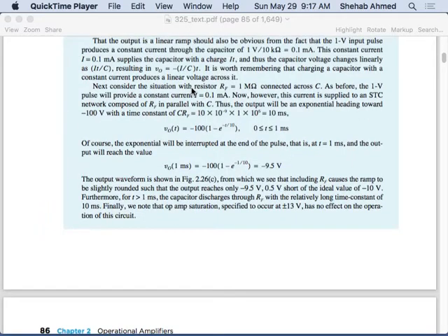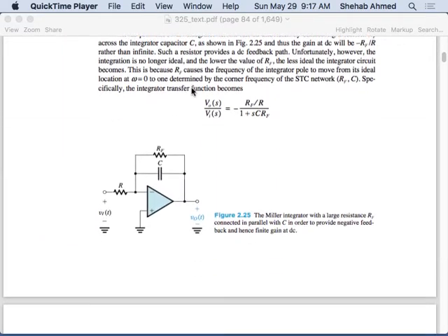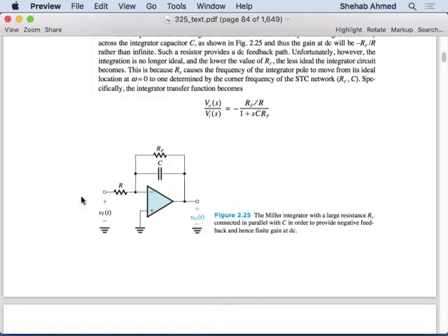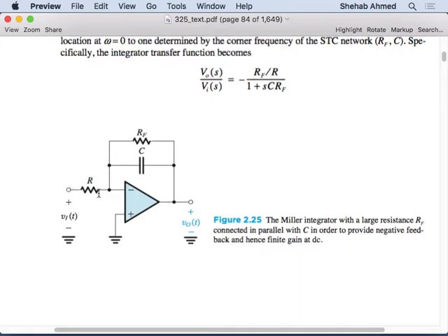We left off last time. I think we were talking about the integrator, and we said that this integrator circuit ideally does not have this resistor in the feedback, right? Ideally, what is the current flowing through here equal to? The current flowing through the resistor. Forget about this RF here. It's this V input divided by this resistance, right?